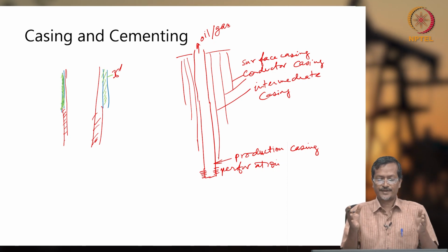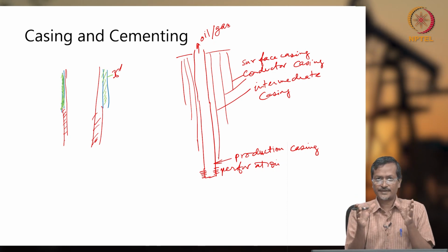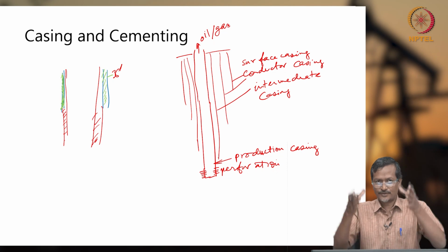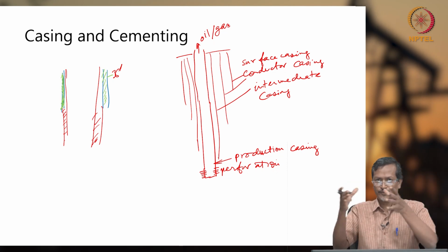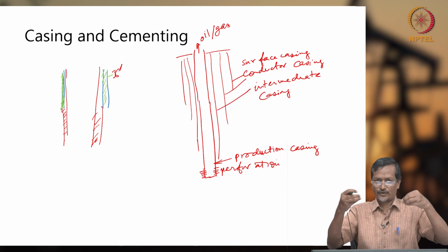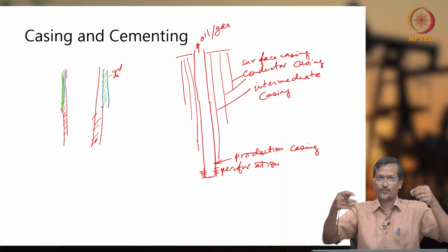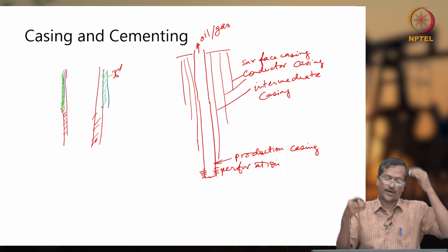And every time you have to cement it, so that the purpose of cementing is that the hole will be stable. Let's say you drill a hole, if you are not cementing, then the pipe will be moving here and there, and then mud will be falling down, and the hole will be unstable. So you put cementing with high pressure. So how to cement it?